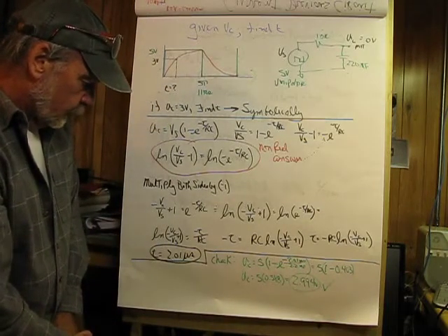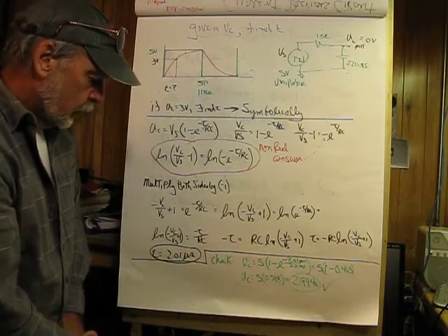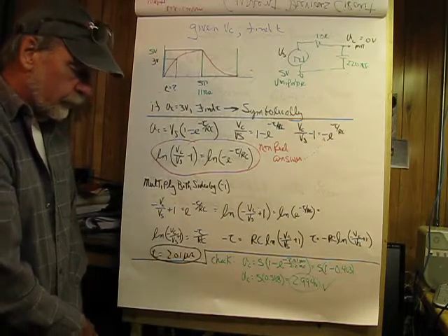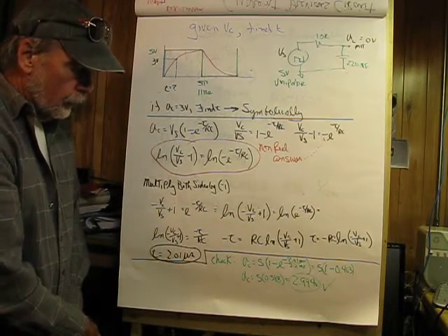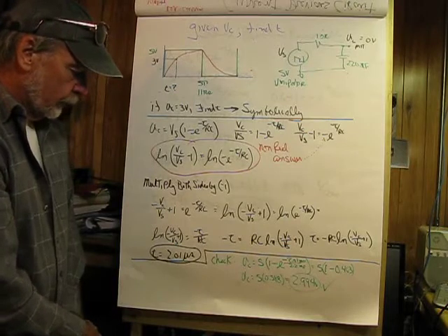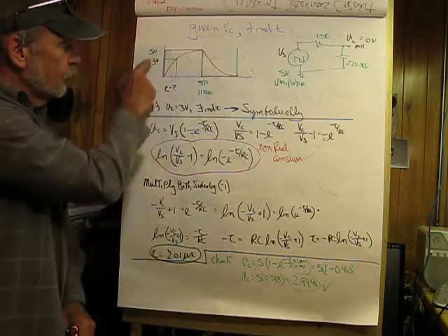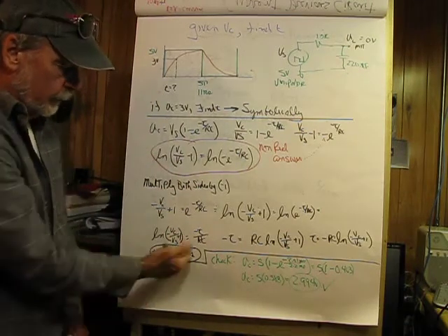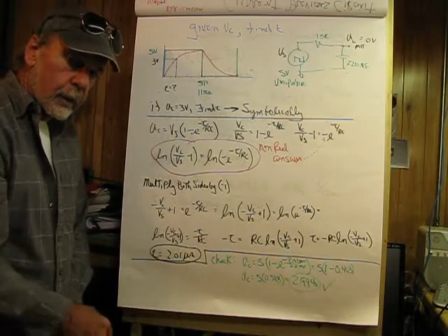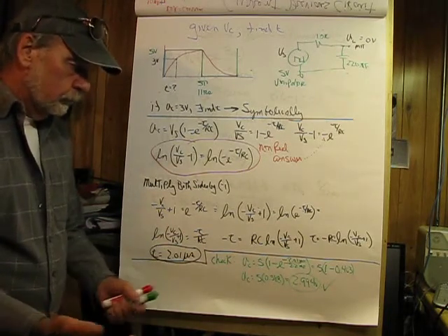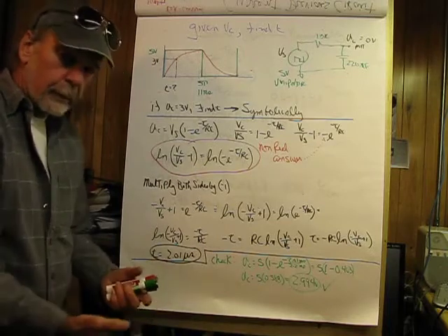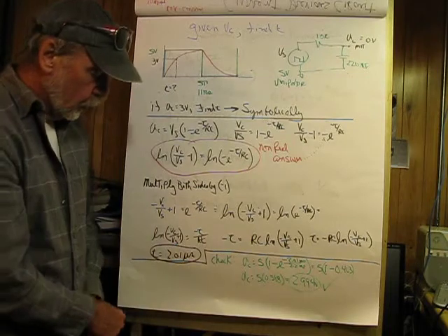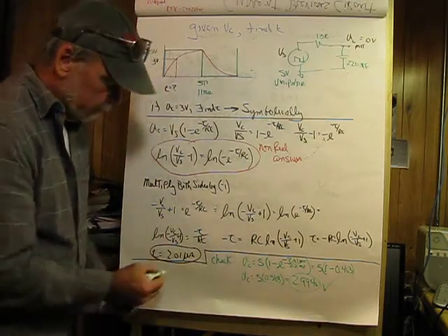If we were to substitute in our values here for our circuit values, what we would end up with is t equals 2.01 milliseconds. Substituting in values simply means that we have VC, which is 3 volts, and VS, which is 5 volts, and the time constant is set at 2.2 milliseconds. By the physics of it, we chose the capacitor and the resistor, and we get this value, t equals 2.01 milliseconds.